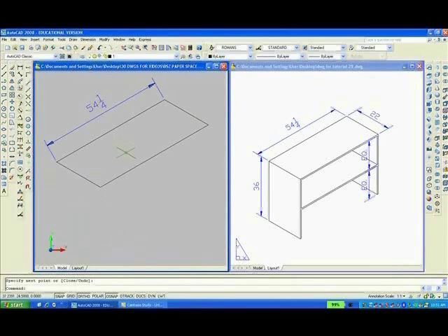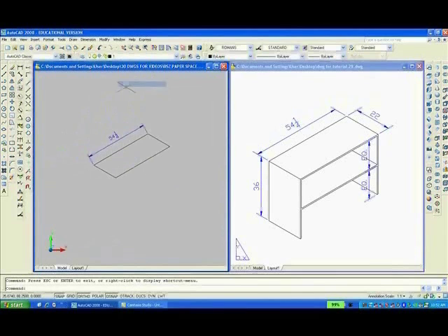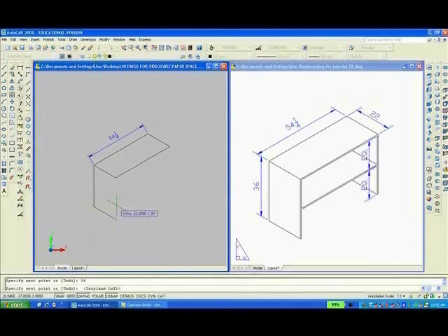Now you hit the F5 key. Well, before I do that, I'll shrink the drawing down in size with zoom real time. Now I'll hit the F5 key so that I can draw a line down, 36, enter. The line's going in the wrong direction, so I'll have to hit F5 key again. Now it's 22, enter. Then I can just go up and close it, enter.